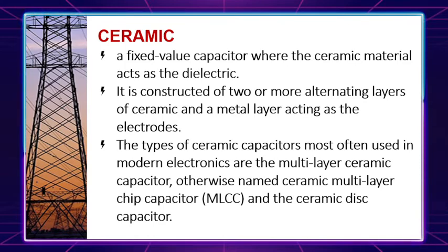It is constructed of two or more alternating layers of ceramic and a metal layer that serves as the conductive plates or the electrode. Of the different types of ceramic capacitors, the most prominent or commonly used is the MLCC. MLCC is the multi-layer ceramic chip capacitor, and the other one is the ceramic disc capacitor.